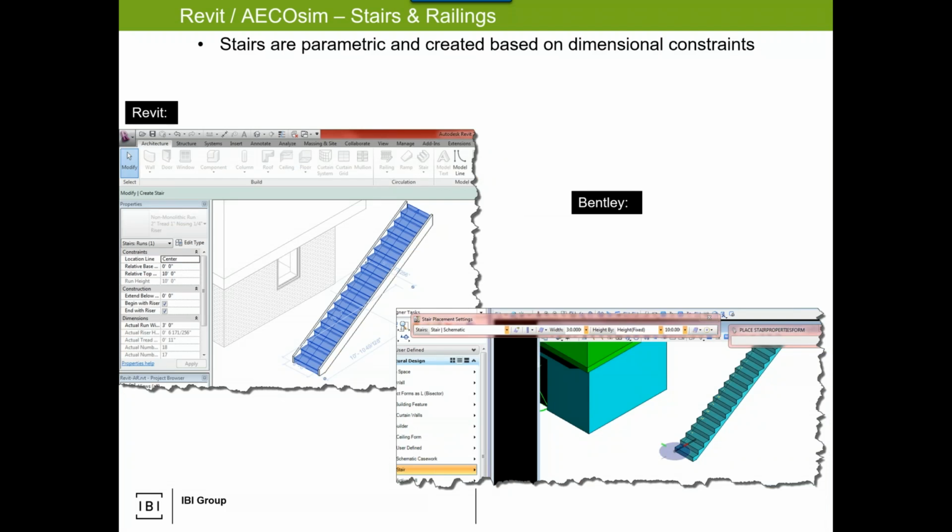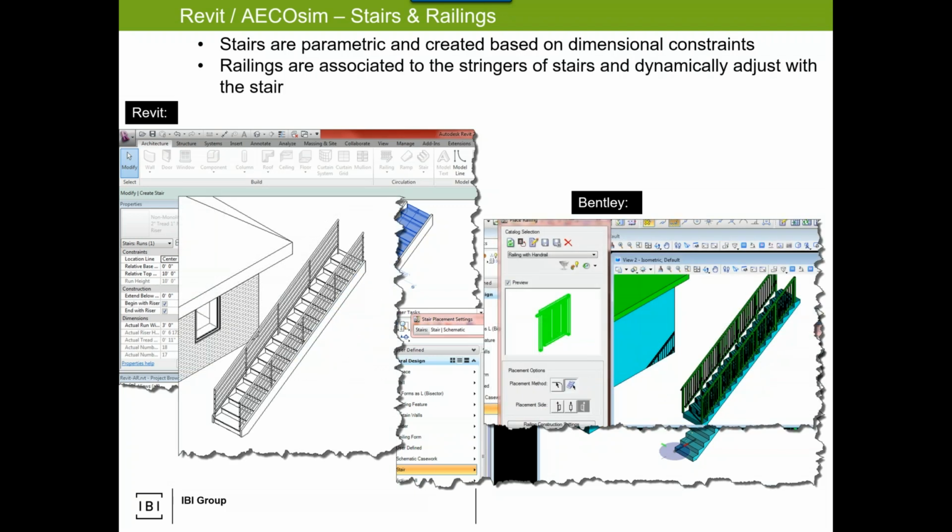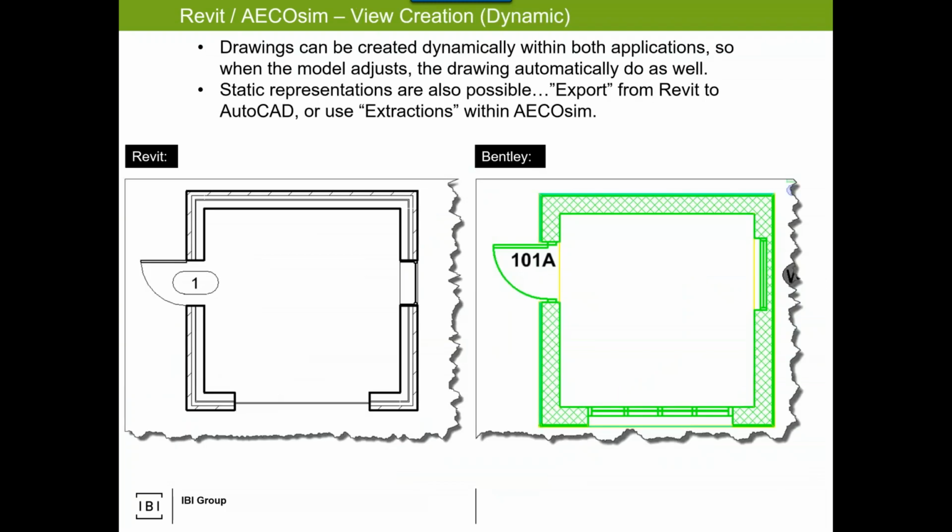Other tools like stairs, showing this because it is the commonality between building authorship tools. It's astounding when you look at stuff like this. And all of these things, different rail types built into the systems, different abilities to build components. As BIM coordinators, it often falls on us. Hey, look at the railing on the left and the railing on the right. Oh, you know what? That almost works, but I need one that does something different. So it comes back to us. Can you help us make the components and ensure that they're quality checked, especially if your teams are not very savvy in the development of content as opposed to just the placement of content?